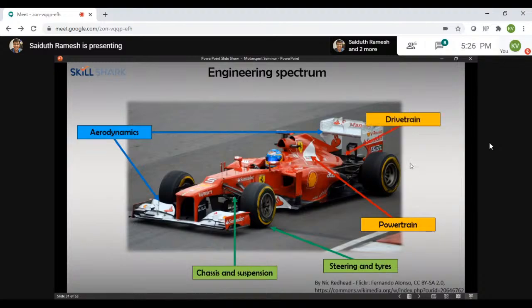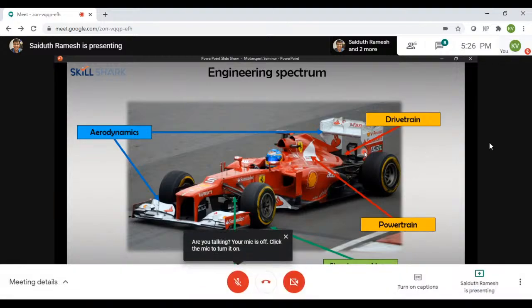And then the final part is the drivetrain, which is basically like a thin line between powertrain and vehicle dynamics, because it has vehicle dynamic effects, but it is linked with the powertrain. So it's basically your gearbox, your drive shaft assembly, something called the differential, which basically distributes torque between the two wheels at the back and stabilizes the car. These are really important parts.